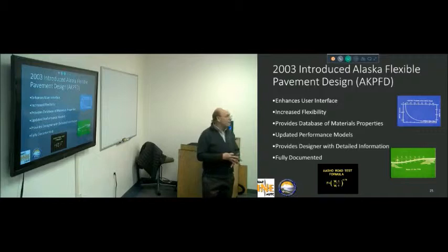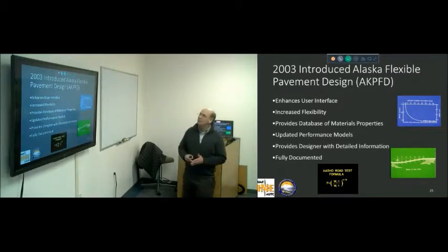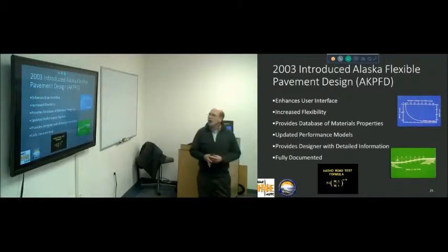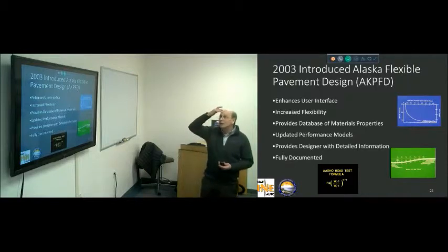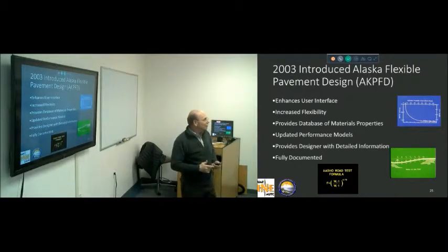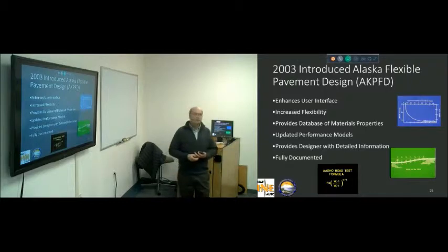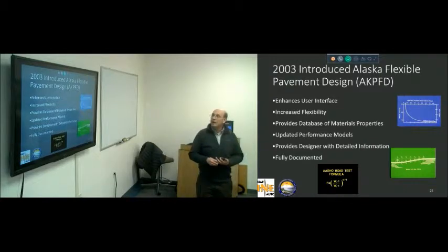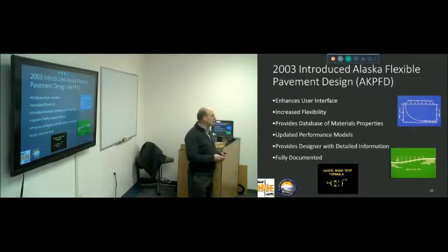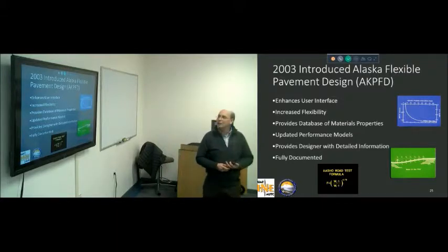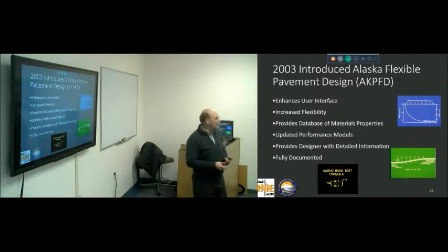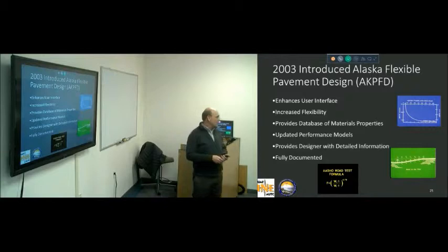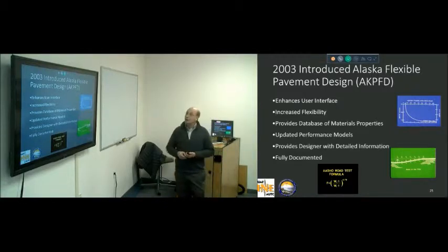And then, of course, we are all familiar with the 2003 Alaska Flexible Pavement Design, aka AKFPD, and that's the one that we're currently using. It did a number of things for you. One is we improved the user interface on that dramatically. We allowed the use of both the mechanistic and the excess fines method in there, which helped. The flexibility in that is amazing, and what you can do if you know how to read all of the outputs out of that. You can actually look at the stress and strains anywhere that you want if you want that level of detail, or it will simply tell you whether it passes or fails, and it will tell you which layer failed, so that you know where to put your attention.